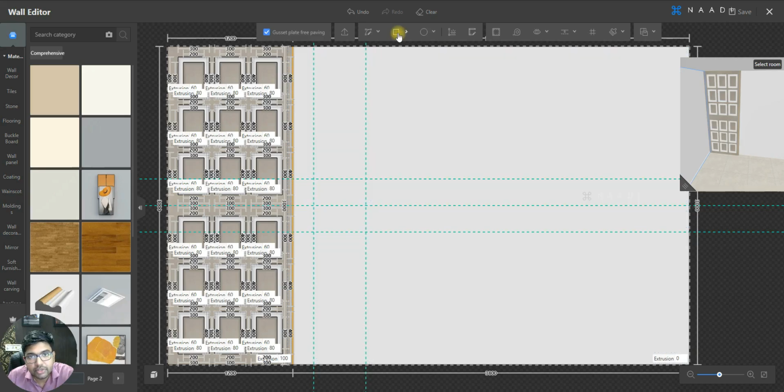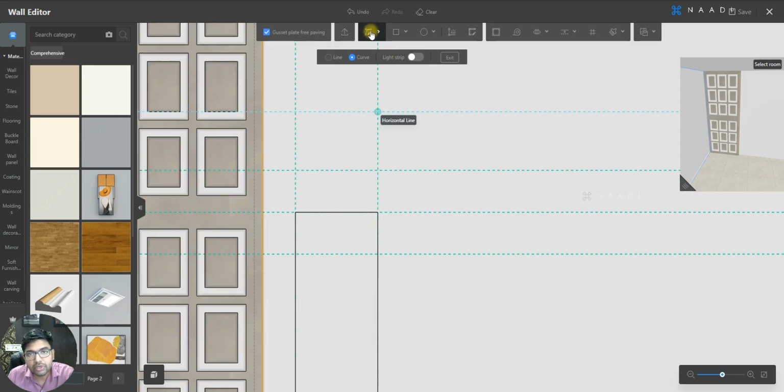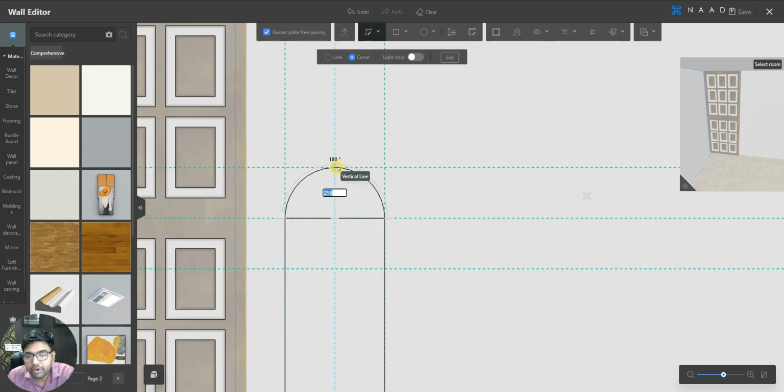So in that, first let me just use my rectangle tool to just draw a rectangle for this part. And once that is done, I could use the curve tool here to create a typical 3-point arc at the top point of this divide. I could just select the starting point, the destination point, and the third point will control the intensity of the curve. So now can you see?